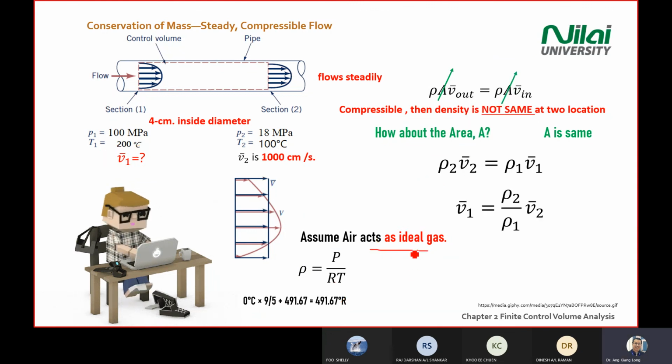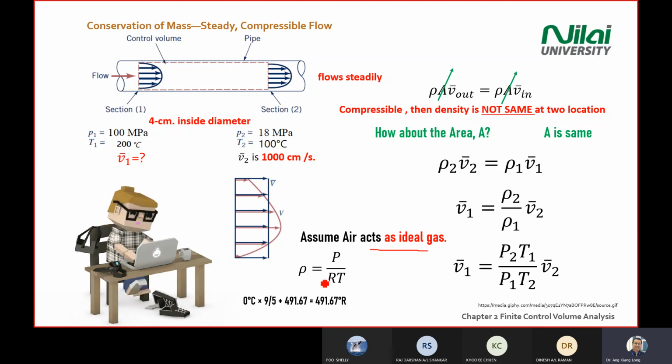So this example is just recall. You need to recall what you learned for ideal gas. Rho equal to P divided by RT, and this equation will not be given in the SM. You need to recall. So you represent why we need to use this equation, because we don't have the rho value in the question. However, we are given some hints that it's an ideal gas. So there's a purpose why we put the ideal gas word inside the question. It means that we want you to use the parameter given in the question to solve.